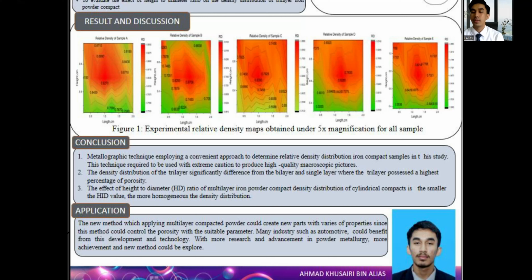This is because the lowest layer of the surface provides the largest mechanical interlocking or nesting for the powder particles from the upper layer to fill the bottom region. That means the first layer has been compacted 3 times, compared to the middle region, the second layer, and the top region, the third layer, which have been compacted 2 and 1 times respectively. As the load was reduced further, the central relative density decreased.